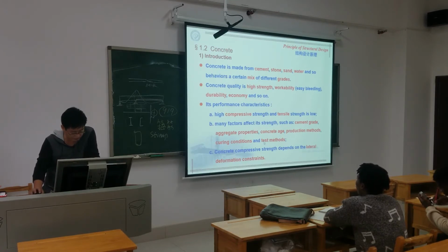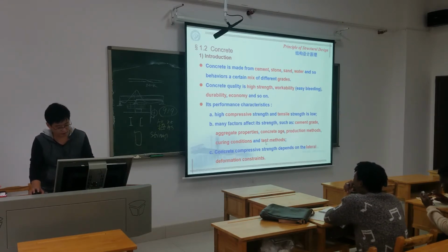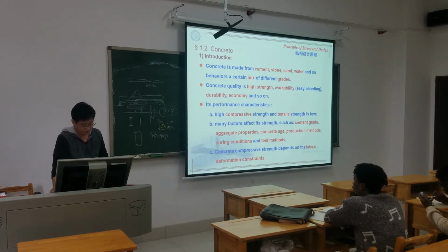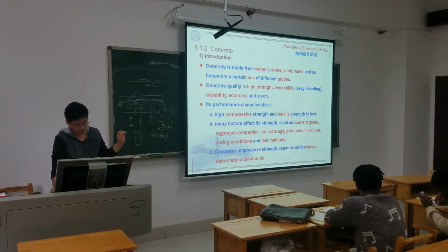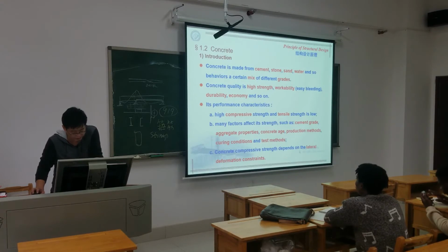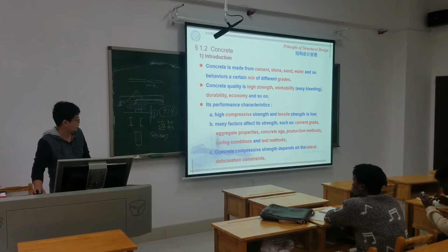And also the test method. The strength value will differ a little, because for concrete there are different methods to represent the strength, and with different test methods you get different values. The compressive strength depends on the lateral deformation constraint. I think this belongs to the test method.